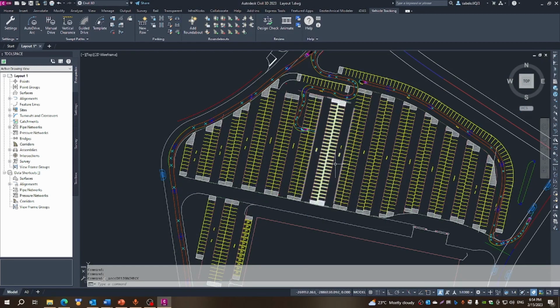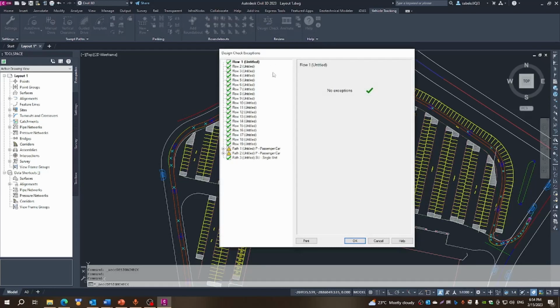We now need to evaluate our vehicle paths against a number of rules-based constraints. We can see that we do not have issues. Let's come and do a design check here. Let's look at the path. We've got some issues with severe steering insofar as the passenger vehicle, but I think that's just due to my own uneasy hand. But insofar as the delivery vehicle, we have got no issues at all. So it does mean that this design of ours is sufficient and will work.